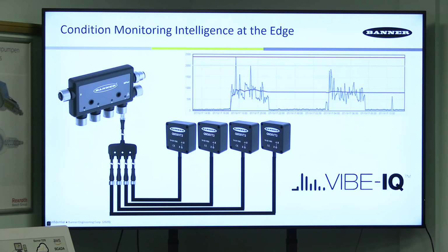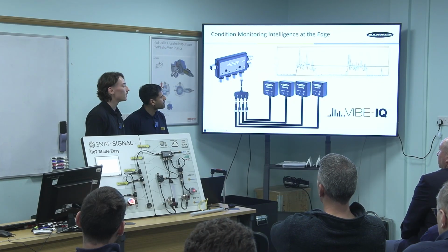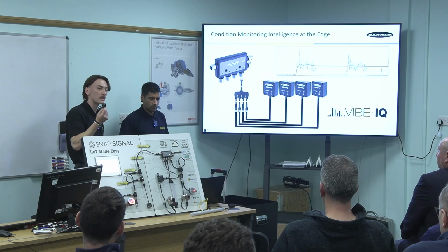So, flicking back to the vibration sensors for predictive maintenance, that's one of these. It's tiny. So that's a Modbus sensor that can communicate directly back to a Modbus master and then send the data out to the cloud. But what Banner have done, nobody's a vibration specialist. They don't know what their motor's supposed to be running out on a good day. So they introduced VibIQ, which is a machine learning algorithm built into the sensor.